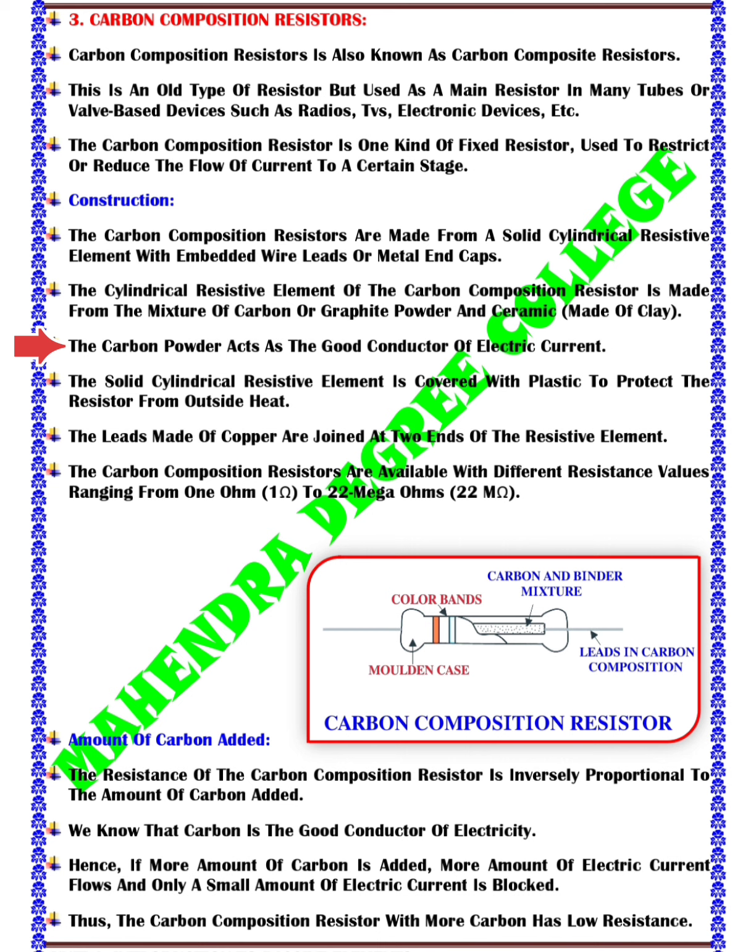It has a solid cylindrical resistive element with integrated wire leads or metal end caps to which the lead wires are joined. It is made of carbon powder and graphite. Its resistance value is determined by the ratio of carbon to binder material. The more carbon in the mixture, the lower the resistance value, and vice versa.